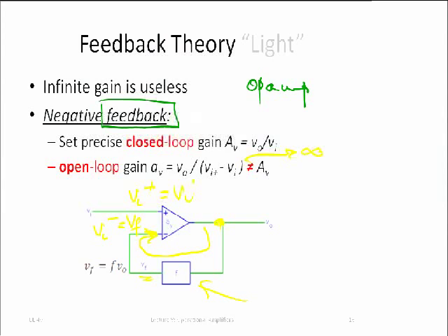Okay? All right, so the main things to take away from here is that op-amps have infinite gain. That's the open loop gain. And then we use feedback, usually negative feedback, to produce a closed loop gain from here to here that is different and has a useful value like 2 or 10 or -5. And those two gains are different. So there is an open loop and a closed loop gain, and those two are different. And this slide hopefully gives the definition of them. And if you still get confused about it, come and ask us. Okay?